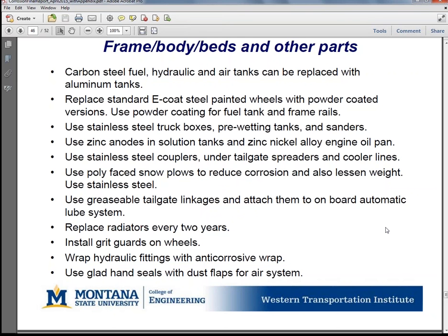Clay, I agree with you, because washing these vehicles at 300 gallons per minute, if you wash it for 4 minutes, that's 1,200 gallons, and that will fill up your holding tanks very quickly. A lot of our sites are not even on a sewer connection, so you have to remove that water and throw it away.